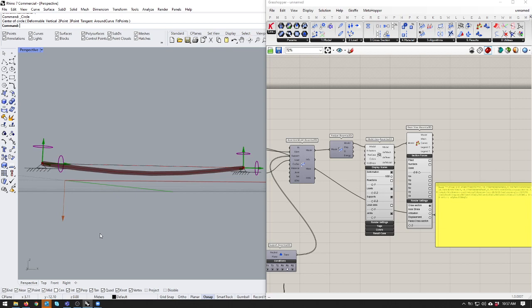We wouldn't use Karamba in the real world to work out deformation. But we have to assume all of our structures are going to deform. So typically on a building like a bridge or a stadium roof, for example, the architects will design what they want the roof to look like, where the roof needs to be once the building's complete. And then engineers will take that model and reverse engineer what the structure should look like when it's fabricated, so that when it is put in place and all the weight of the structure is applied to it, it deforms into the position the architect has designed.